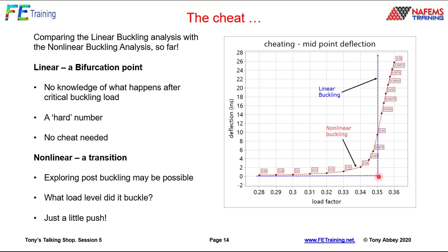If there's evidence of a structure starting to have some behavioral response pre-buckling point, it starts to what I call moan and groan a little bit, and then it buckles, then it's almost certainly the kind of structure we need to do a nonlinear analysis in. This one, it's kind of on the fence. We could or we could not. We get very similar results.